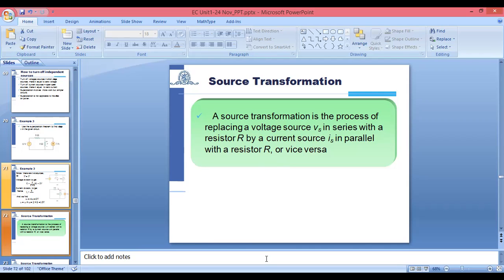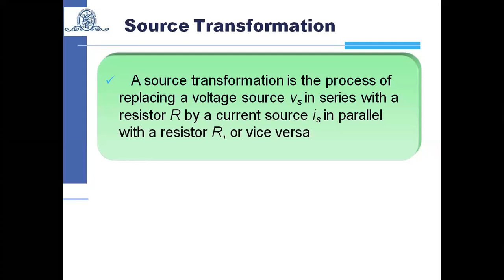So when we have any linear complicated network, we can convert that complicated network into a simple voltage source and a resistance. That resistor will be in series with that voltage source. We call that circuit a Thevenin circuit. If we are supposed to solve any complicated linear network, to derive Norton's theorem,